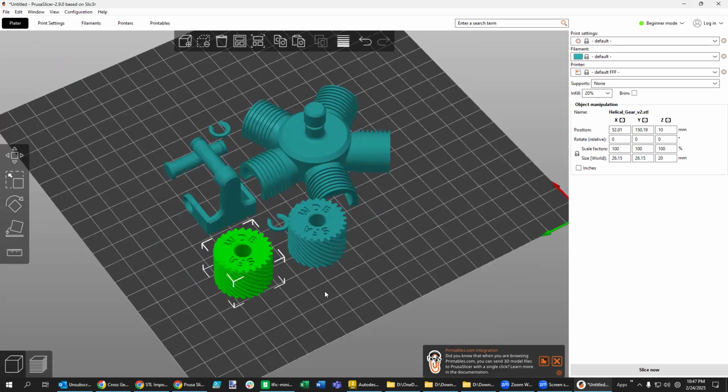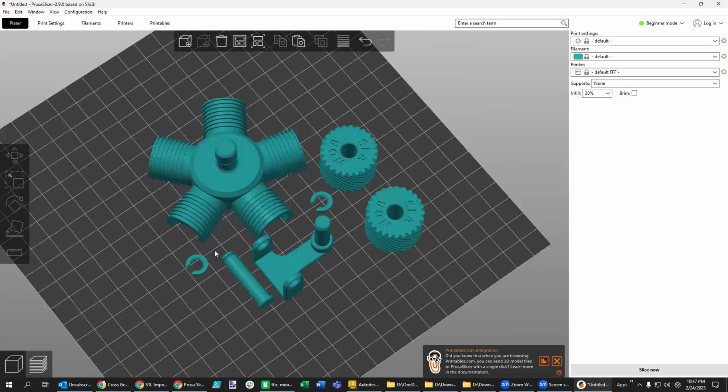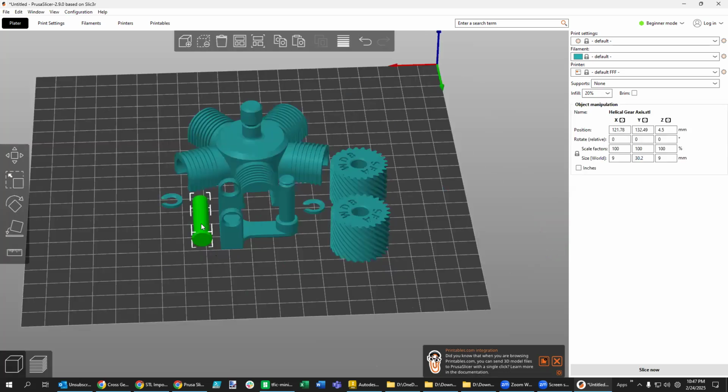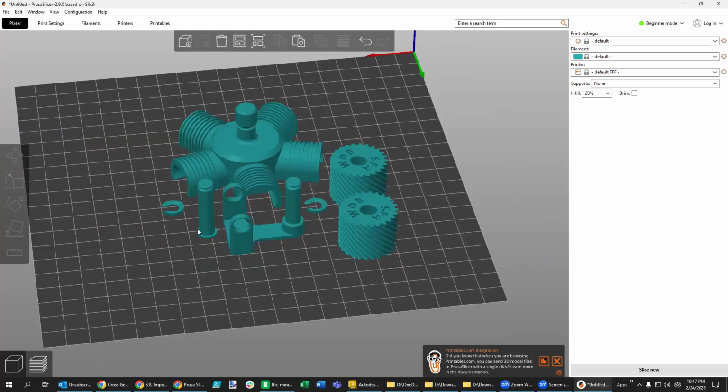And of course, one of the things we see is we don't want this to be printing like that. We want it to rotate. And I'm not really sure how to do that, but look at this over here. That says rotate. This says face on face. So that means select the face to go down. So it's a little bit different. You have to do 2 clicks there. So this one, we don't want to print it sideways. We want to place it on this face. Slightly different.